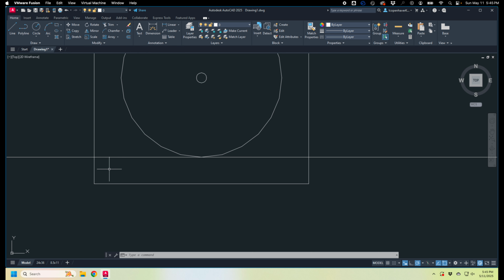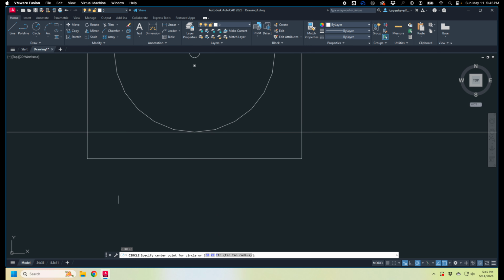So I want to put, let's say, 3 bolt holes. 1, 2, 3, in this section. Those bolts are going to be, I'm just arbitrarily deciding, 1/4 of an inch bolts that I'm going to use. So those need to be oversized by a 32nd of an inch at least. So I'm going to say a diameter, and then 1/32 more than 1/4 of an inch is 9/32nds.